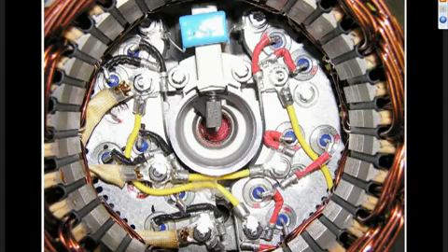And on one of them you can see the little spring behind it. The brushes are spring-loaded so that they press against the slip rings on the non-drive end of the rotor shaft, which has been removed from the alternator to take this photograph. So those are the basic components of this thing.